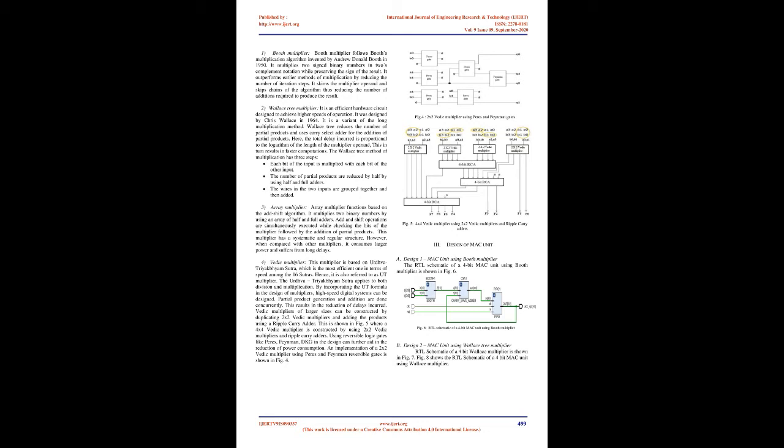In 7, a 32-bit MAC using the Wallace tree multiplier was implemented on the Spartan XC3S500E FG320 device and synthesized using 90nm technology using Synopsys Design Compiler, and its results were compared with the conventional MAC unit. A 32-bit MAC unit using a Vedic multiplier and carry save adder was proposed in 8. The delay incurred, utilization, and the number of LUTs required were compared with existing designs. In 9, the procedure for multiplication using Vedic mathematics is proposed, and the results show that the time complexity involved is lesser than the conventional ways of multiplication.